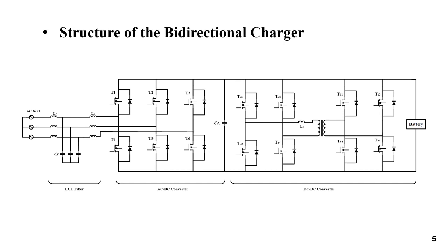This bidirectional converter, which allows electricity to flow both from and to the car battery, may be made to accommodate a variety of charging power levels. It is connected to a dual active bridge DC to DC converter. The isolation provided by the transformer between the battery and the grid is one of the most crucial aspects of this design, and it is crucial for a number of reasons, including safety. The dual active bridge can guarantee appropriate V2G and G2V operation of the car because it is a bidirectional converter.